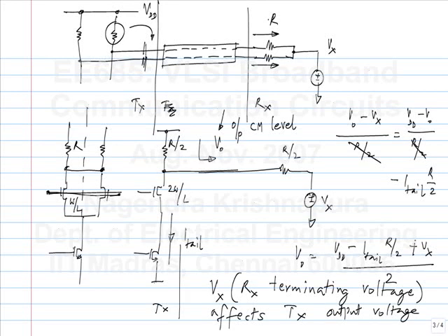Okay. So here it's not like there is one particular answer that you use always. In fact, in practice also there are many choices. I am just asking you to give some choices and evaluate it. One is, of course, you do AC coupling, then you completely make the receiver DC picture independent of the transmitter DC picture. So that is fine. There are some disadvantages to that. We will discuss it soon. But one thing is, okay, let's say I want to transmit very low frequencies. In that case, AC coupling may become difficult because you have to use very large capacitance and high impedance.